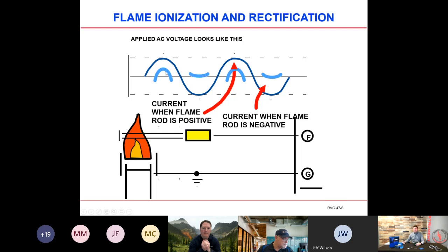The reason why that shows the AC signal in this format is because of this earth ground. This earth ground needs to have a ratio of about 4 to 1. So the ground needs to be about 4 times larger than the area that you're sensing inside of this flame envelope. That's how we get the bottom end here looking like, it almost looks like a DC pulsating signal. And we do this by the rectification circuit and this ground here that's attached to the burner assembly.